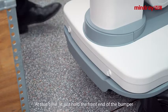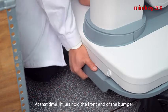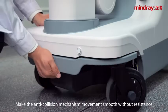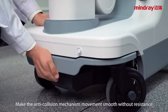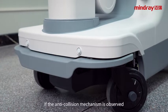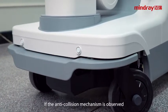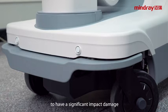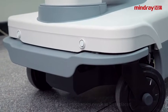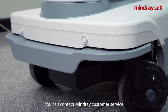At that time, just hold the front end of the bumper, press down and shake the bumper. Make the anti-collision mechanism movement smooth without resistance. In general, the problem can be solved. If the anti-collision mechanism is observed to have significant impact damage, it needs to be replaced. You can contact MobiEye customer service.